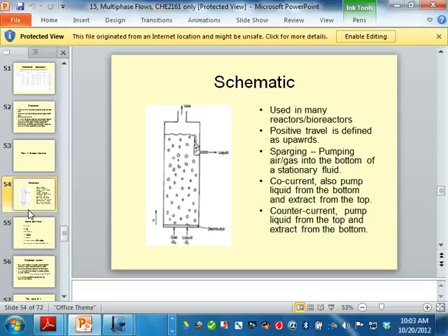maybe you want some reaction to happen. So you want maybe some reaction happening, maybe you're producing the gas, or using the gas as a catalyst, or using the air just to do some gentle mixing or whatever. So that's the application. I'm sure there are a lot of applications. Sometimes the gas, the air, is used to collect or trap oil, so you want to do oil liquid separation. Sometimes you want gentle mixing, so you pump gas instead of using a mechanical agitator.